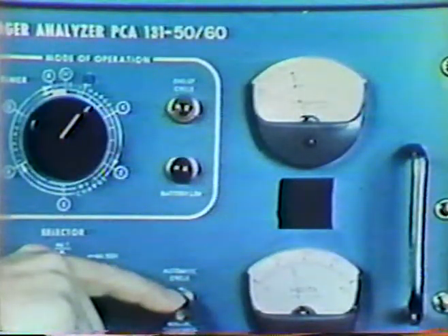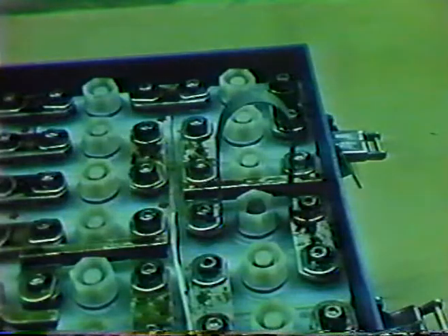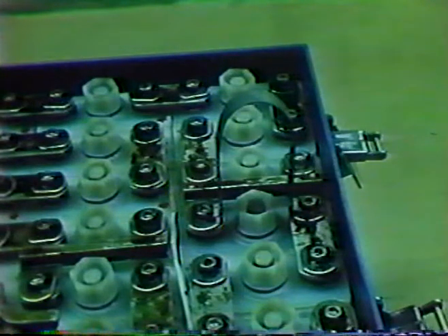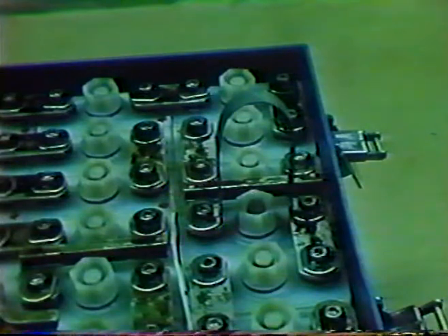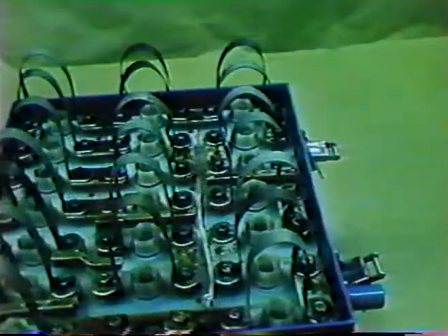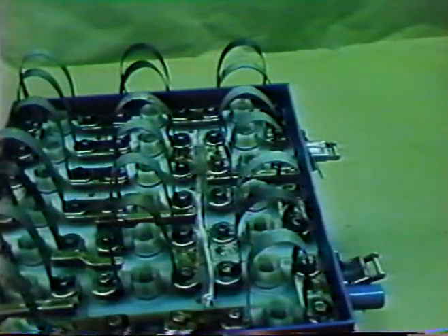Discharge the battery at a lower rate than before until the individual cell voltage is about 0.2 of a volt. With the battery load still applied, individually short each cell with a shorting strap. Allow the battery to sit for 3 to 8 hours in this condition to allow all the cells to become completely discharged.